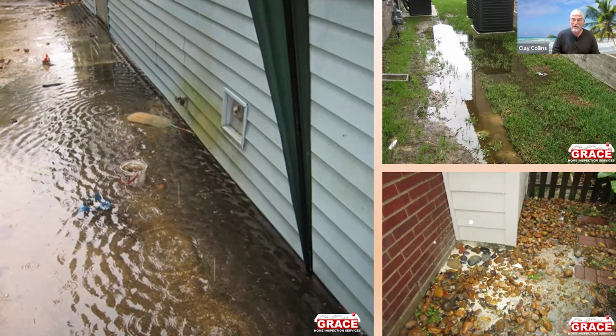You'll also see that the only way to establish a drainage swale is going to be to take out a lot of dirt. And the homeowner, home buyer, probably doesn't even think about that, but we wouldn't have had that good a picture if it wasn't raining. Top right, there's that drainage swale. It's holding water. Look at how much clearance you have on the slabs. It's very visible on the right-hand house, not so very visible just because of the angle of the picture.